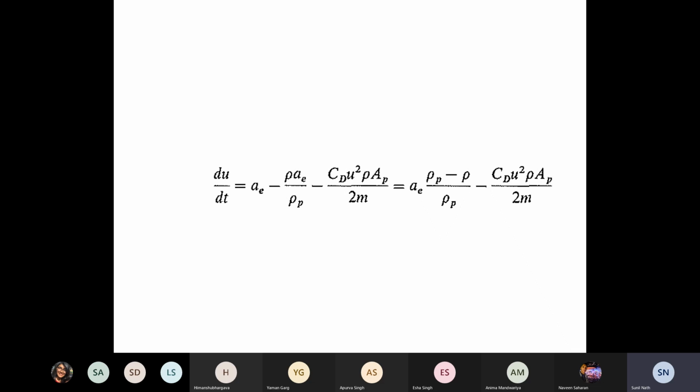Whatever we discussed for gravity is also applicable for a centrifuge. The only thing is that centrifuges come in very complex geometry. For instance, they have vanes to increase the area that you can give for the settling, and a very conical type of arrangement, or a disc type centrifuge as it's called. If it were just a simple cylinder, it would be much easier to do all the geometry. You can use this R omega squared very easily, but they come in all sorts of shapes and sizes.